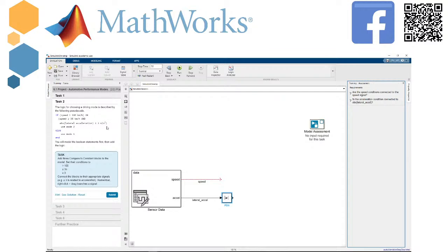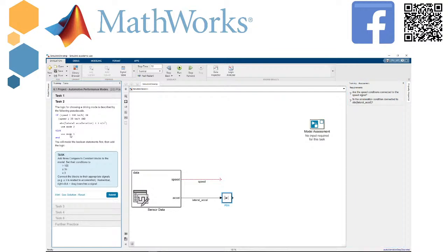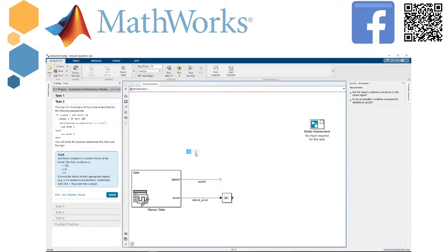I will show you that we need to work on the function. The MATLAB function has been pre-populated with values of the constants. Double click to open the MATLAB editor and then add the equation such that delta H is the input and the turbine power is the output. So we need to write this equation inside the function. Double click on it.